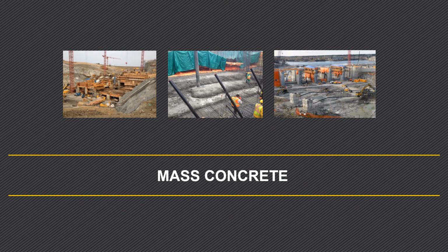Now, as I said, the focus today of our presentation is going to be on mass concrete. And the opportunity for mass concrete to discuss different topics related to the thermal aspects of concrete is very good. Because we're going to be able to talk about the ability of the concrete to generate heat, the temperature of concrete at placement time, and even then the temperature limits associated to controlling thermal behavior of concrete placements.